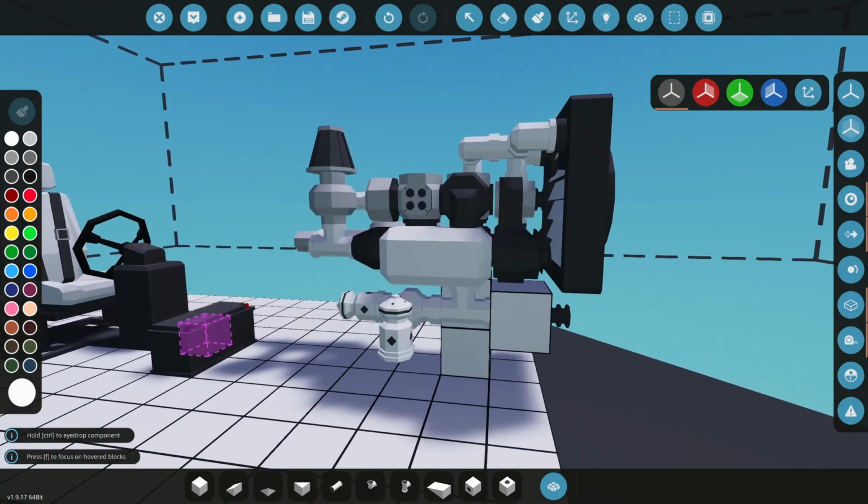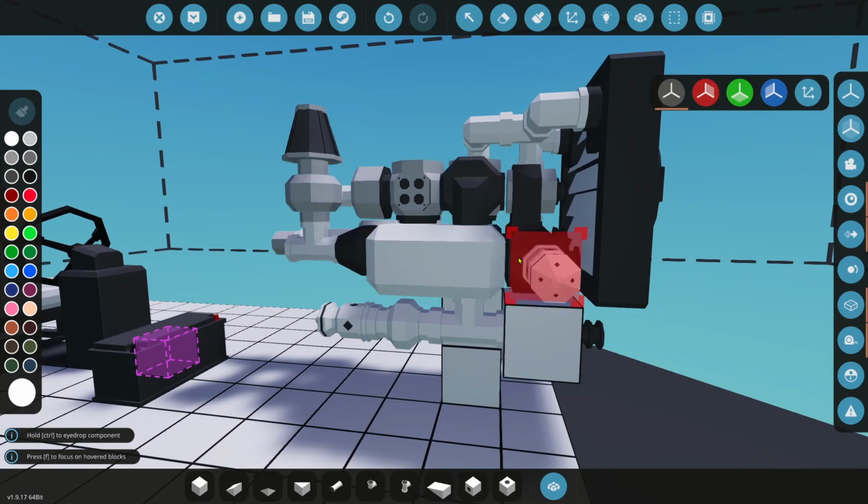So what this is going to allow it to do is, if the pressure in this tank is greater than the outside atmosphere being 1, it's going to let the higher pressure leak out to the lower pressure and equalize. So if the atmosphere in here was, say, 2, that will let it equalize with the air pressure. You need to do this or else you're not going to be able to fill your tank. If the air pressure in here was, say, 10, you would not be able to get any fuel in there. You're also not going to reliably be able to get your fuel to come out, because you need to replace that fuel volume with something. You need to replace it with air.